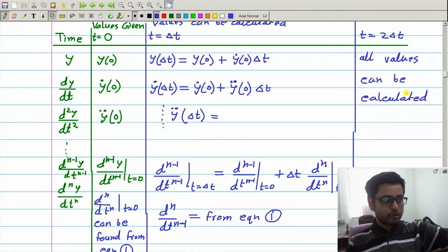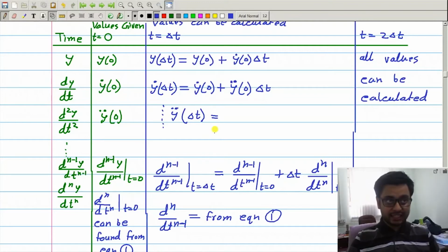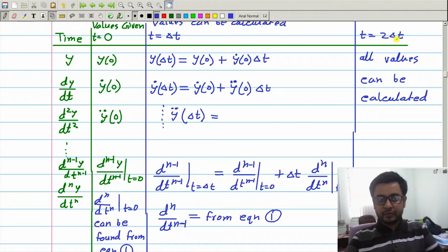You can check it also in this way, what we did yesterday, starting from all 0 initial conditions and input also 0, calculate the output at next time instant delta t, you shall get 0, all the other derivatives also will be 0, and this way if you calculate output at subsequent time instants, you will get all 0.